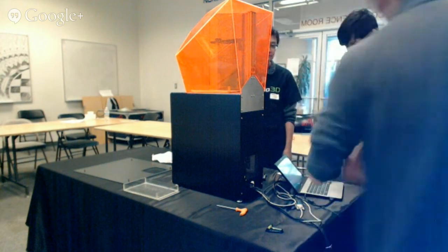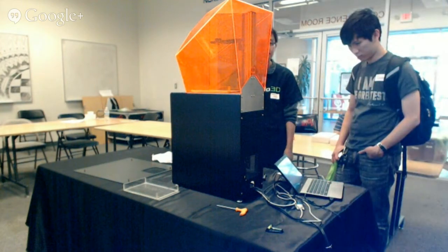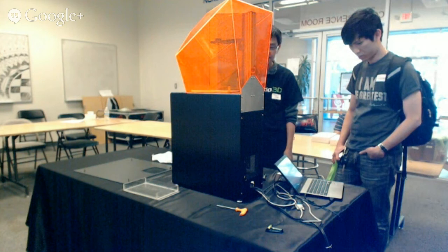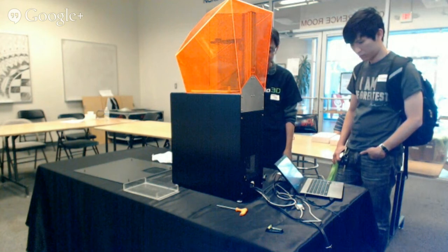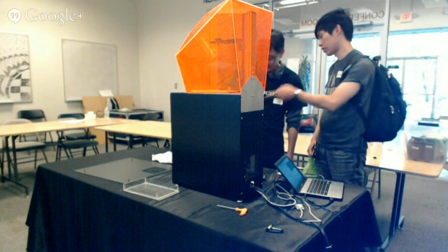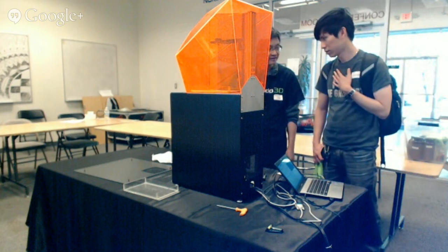These oftentimes will change with your part design. If you've got a part with changing surface area in different places, you would align this to where those surface area changes were, to try to mitigate some of the forces.